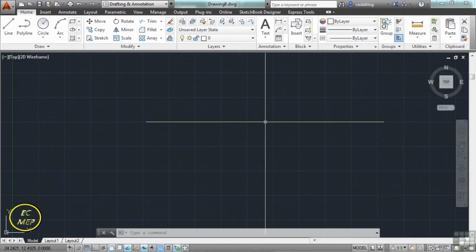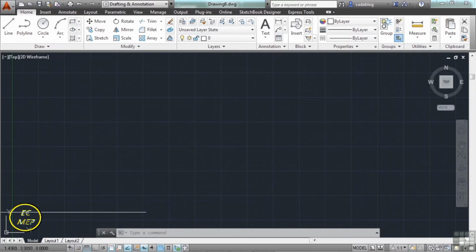How does AutoCAD know where your objects are? Well, it uses a Cartesian coordinate system known as the User Coordinate System, or the UCS. When you turn AutoCAD on and opened up a drawing, you might have noticed the 2 arrows that appear at the bottom left portion of your screen, down here. That is the UCS icon. It's there to help you keep track of your coordinate system.